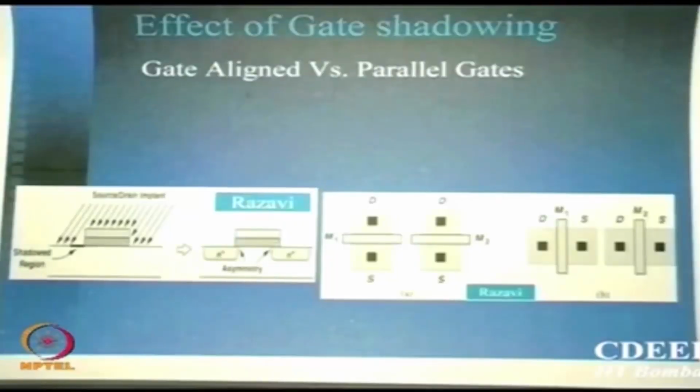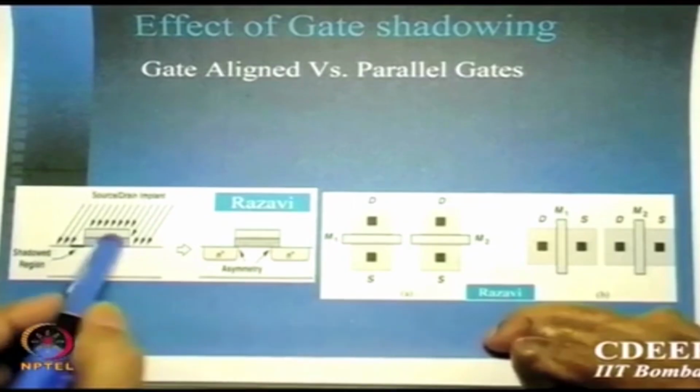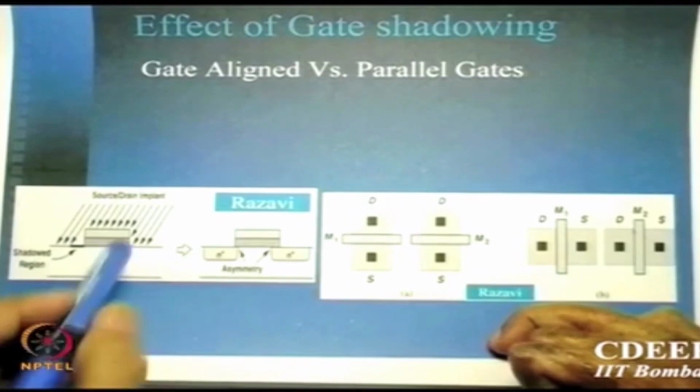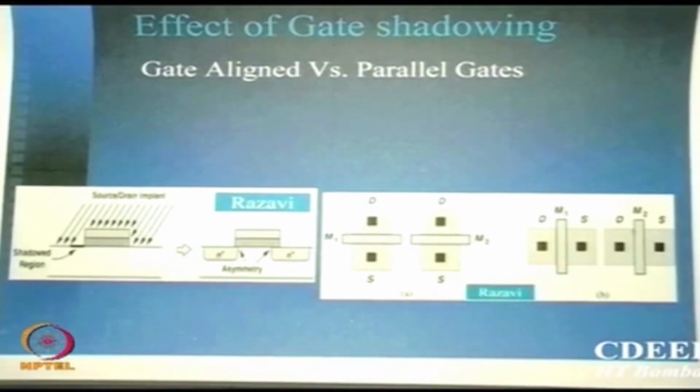Is that okay? There is another worry which analog people get problems with. Here is another problem which we observe. When I was making that N-channel device, I have this oxide and gate delineated first and then implant source and drain. But it is the way the implantation process goes, many of you might not be aware; those who are doing the technology course in our other department might have seen implants already. There is a columnar tube, maybe of any size, 8 inch or 12 inch, through which ion beams of a particular dopant, or whatever implant you are doing, are focused by electromagnetic fields.